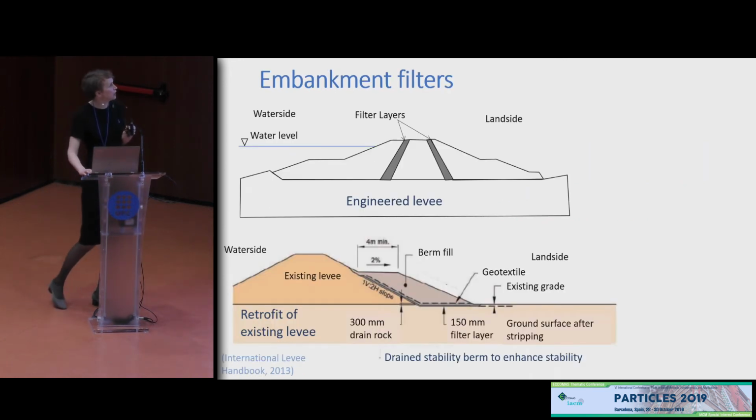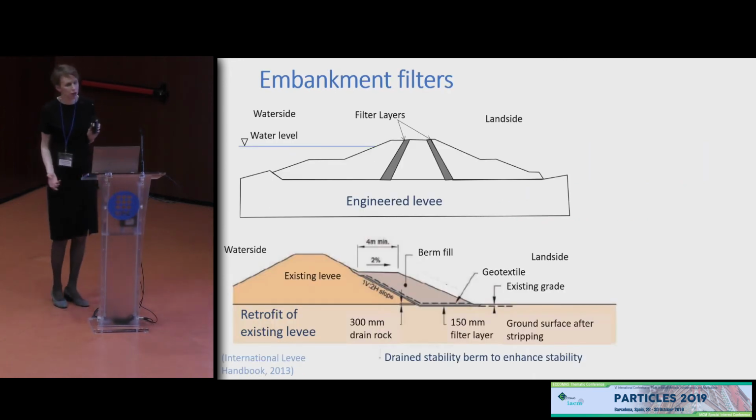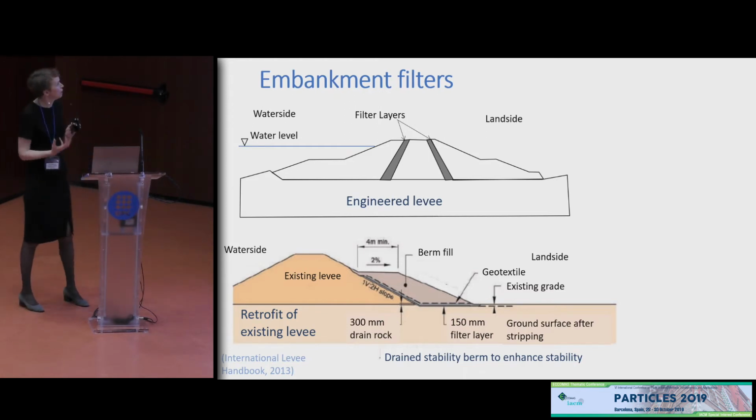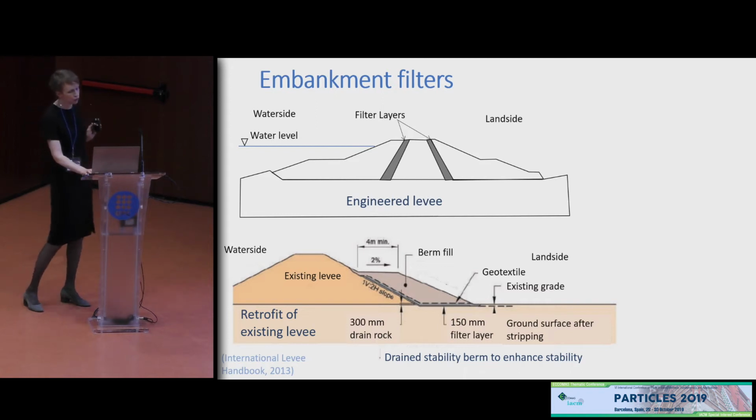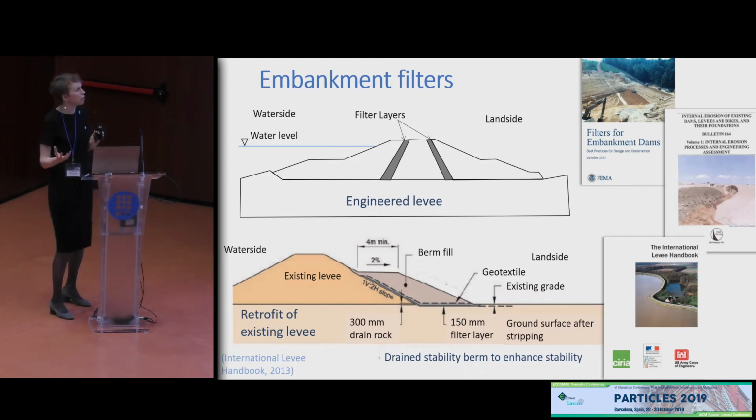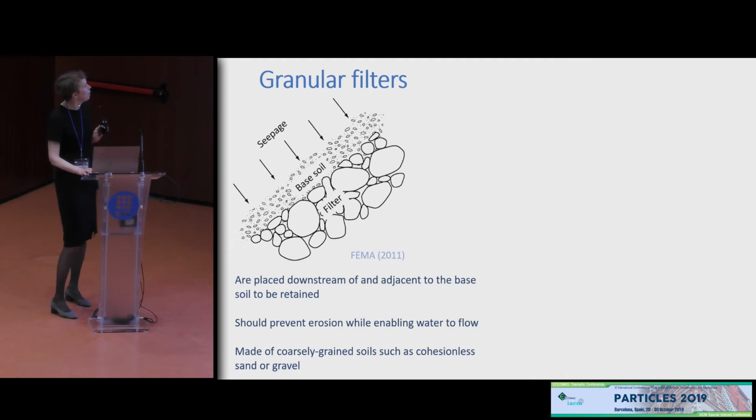Seepage is obviously a significant issue. I've already mentioned the problems at Bennett Dam. But filters and filter design is an issue for engineered levees, dikes, or flood embankments, as well as for embanked dams. And the design of filters has been addressed in a number of recently developed guides for practice. Filters are a key element of flood embankments or embanked dams.